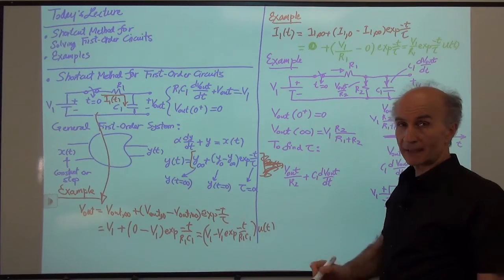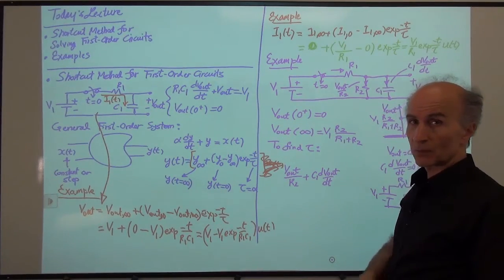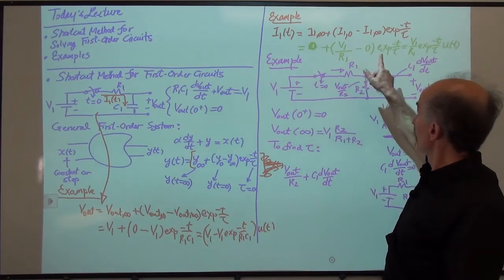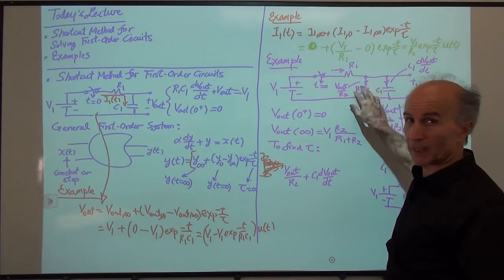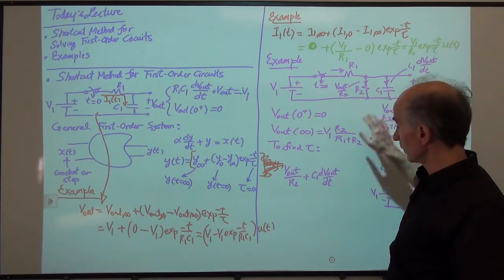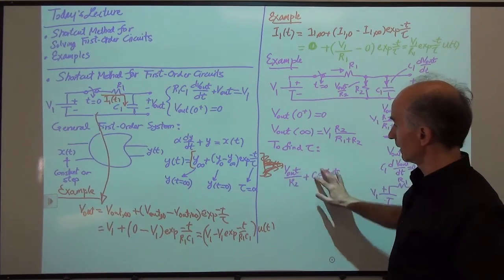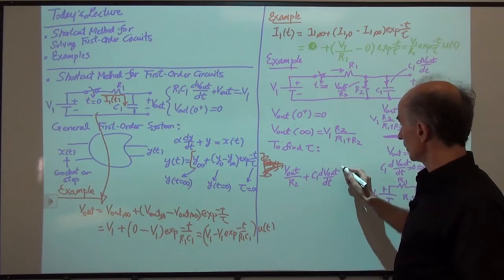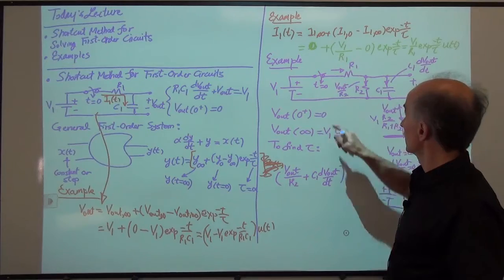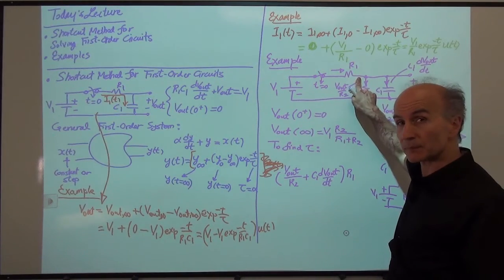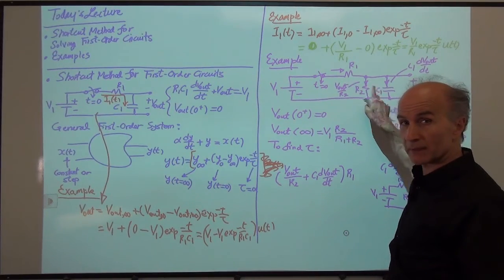Now here is not exactly node analysis, because for node analysis you would say V1 minus V out over R1 is this current, right? And then you would equate that to these two. You could do that, or we can say that these two multiplied by R1 give us this voltage, right? This current plus this current is this current.